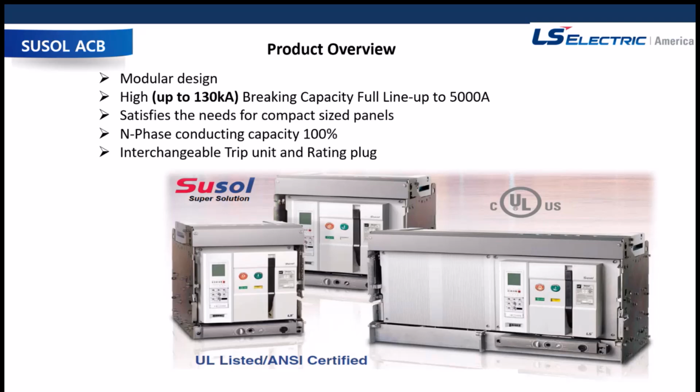Modular designs, up to 130 kA breaking capacity, and a full lineup up to 5,000 amps. I think we even have a UAH, we have 6,000 amps available. It satisfies the needs for compact size panels. We do have a compact air circuit breaker, very limited in stock, but they can be ordered. The conducting capacity of the neutral phase is obviously 100%. So we have 100% duty on air circuit breakers, unlike molded case circuit breakers that have 80 or 100%. Air circuit breakers are all 100% here from LS Electric. Interchangeable trip units and rating plugs are available, and we do have them in stock.